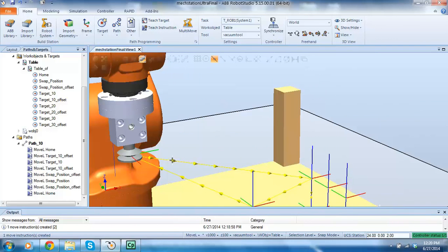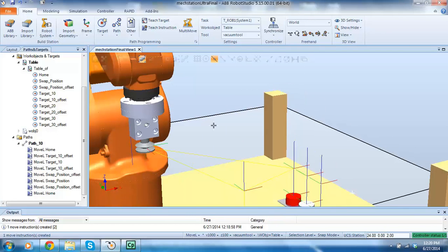And sometimes it finds a point along the line, and for whatever reason it can't calculate that point. Probably doesn't make any sense to you. Hopefully your brain is saying, well, screw the move L command, why don't you just use a simple move J, a move joint, where you just give it the start and the end point. And that's one way you can do it.